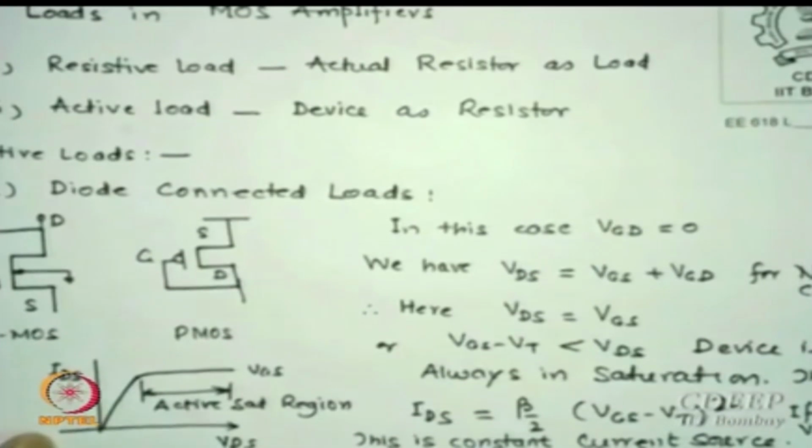Now I will show you what is important for us in a good current source: it should have a large parallel resistance to the current source, that is the better one. So we will evaluate for this case the impedance seen by this device as a load, and that is essentially the feature of how good the diode connected load will be. Is that okay for those who have written down now? So if I wish to figure out R0, I put an equivalent circuit as I did earlier.